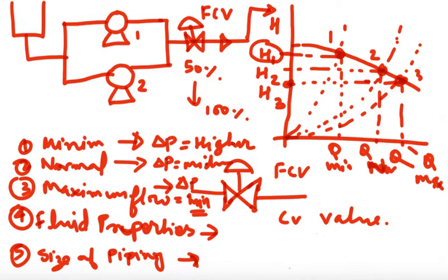When I'm discussing what a process design engineer does, you can understand what our input is and how precious these values are for the instrumentation design engineer and further buying and procuring this control valve. So based on our operation, pump operation or process requirement, we know what our fixed head requirement is here and what the available pressure drop could be for FCV while operating at different flow rates.